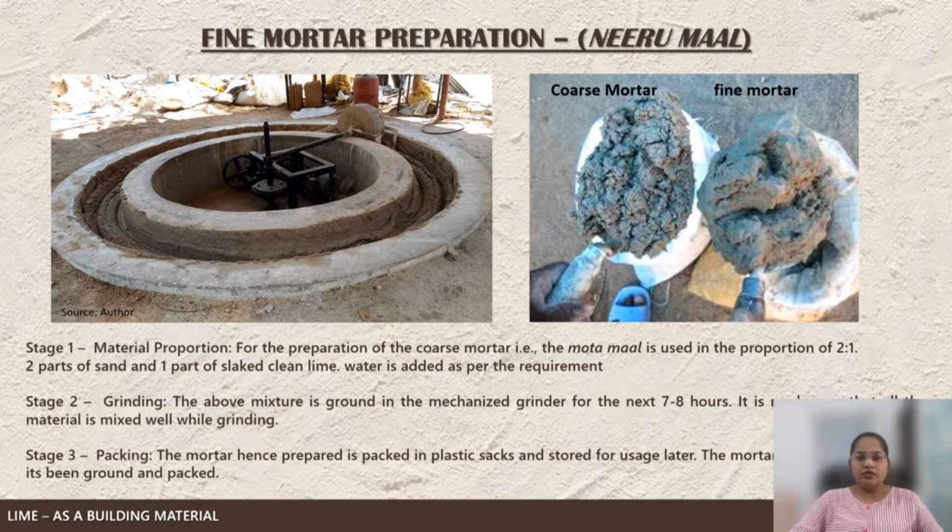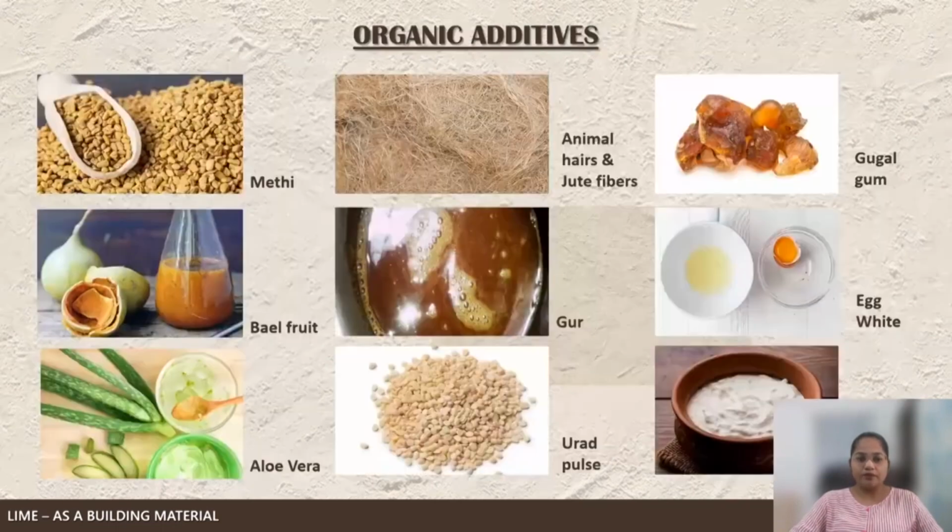The above mixture is ground in a mechanized grinder for the next 7 to 8 hours, and make sure that all material is mixed well while grinding. The mortar thus prepared is packed in plastic sacks and stored for usage. The mortar is used 2 to 3 days after it has been ground and packed.